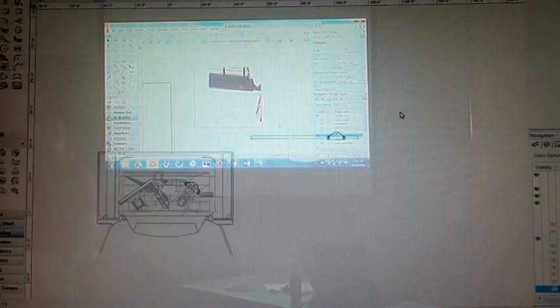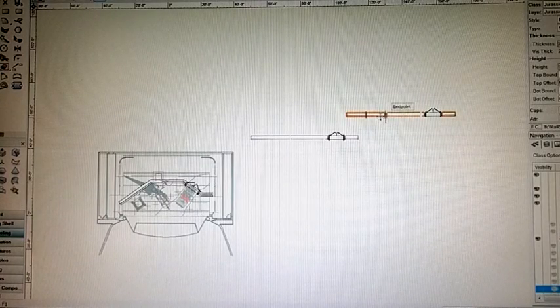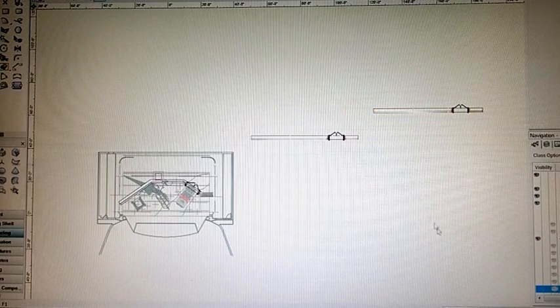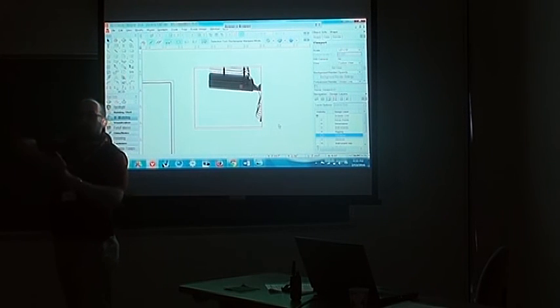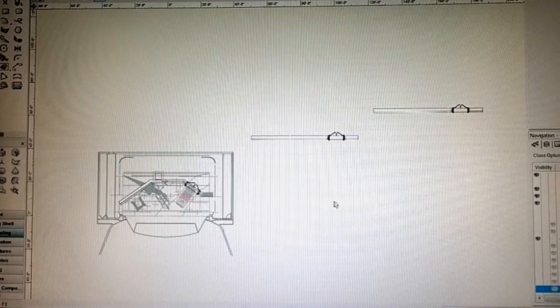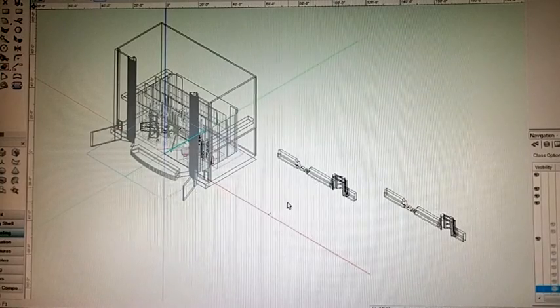If you have a lot of different objects you're creating elevations of, what I'll do is I'll stack them diagonally. That way, if I want to do a right side view of something, and there's another object here, I can get a front and a right side view without them interfering with each other, if they're on the same class or the same layer, right? And sometimes I'll do that as well. I'll just create a new layer for elevations, and all these objects will be on the elevations layer. That way I don't have to look at all these extra objects when I'm in 3D.